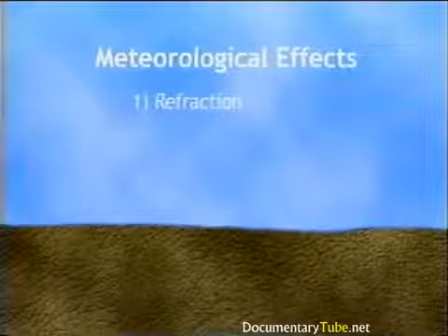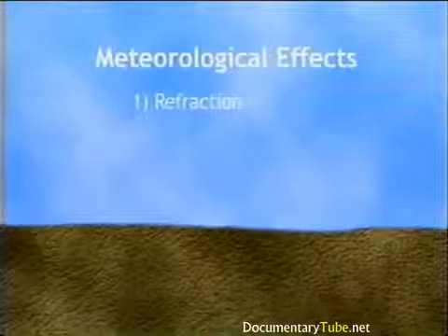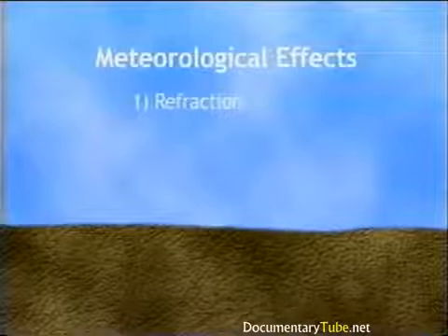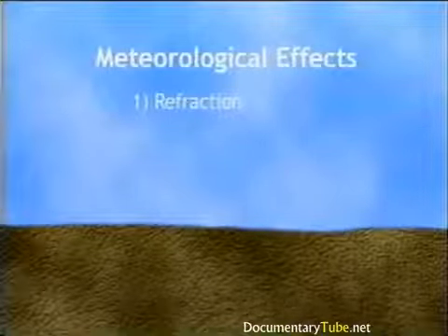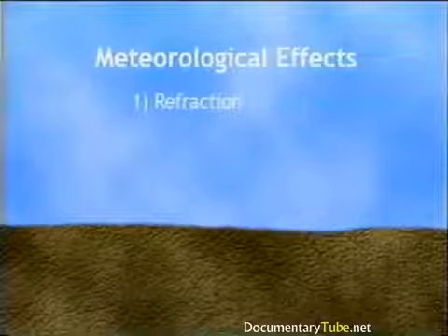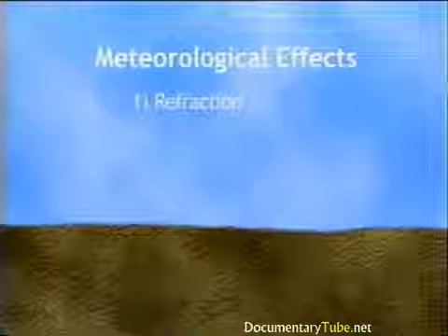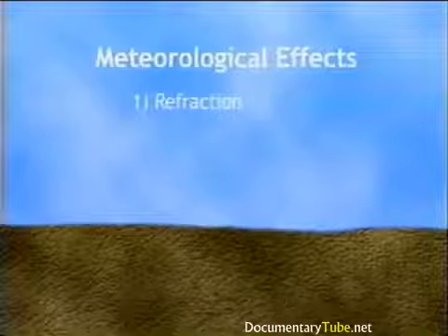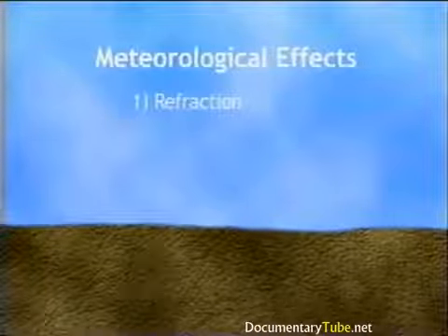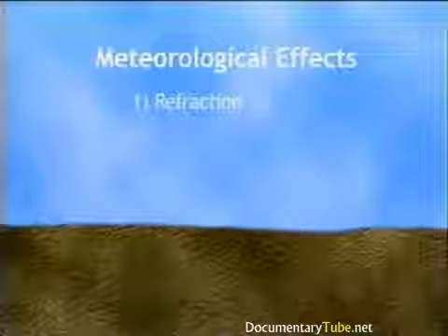It should be noted that while atmospheric conditions can have major effects on propagation of sound over distances greater than about 100 meters or 300 feet, typical highway studies are performed within 100 meters distance from the highway, in areas where the meteorological effects would be less severe.